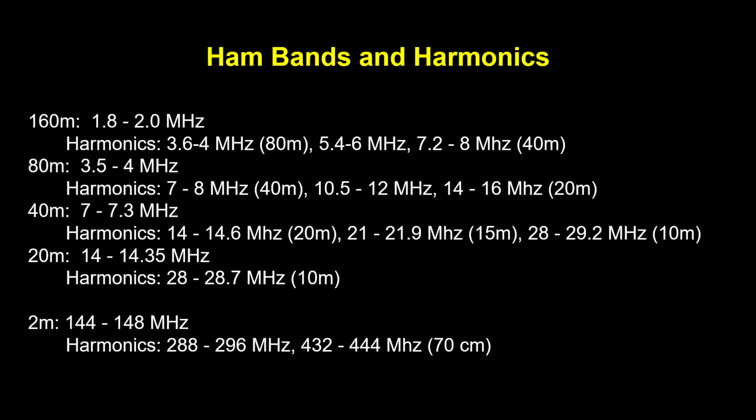We need to ensure that these radios meet the emission standards as well as some of the other standards required for transmitting on the radio band. And that's where the interesting part comes. You have to do the measurements yourself, or be able to trust the company from whom you purchase the radio that it's compliant, because ultimately you as the ham radio operator are responsible for the emissions that you cause on the airwaves.